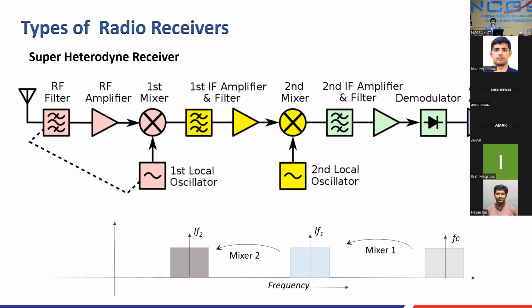I can share an example of one of my implementations where we have a 100 megahertz to 1 gigahertz input signal. Then the tuning LO was around 2 to 3 gigahertz. Then the center frequency was 2 gigahertz 50 megahertz. Then it was again down converted to around 188 megahertz with 100 megahertz bandwidth. So at IF, it was a 100 megahertz bandwidth signal with a center frequency of 188 megahertz, which could be easily sampled by 600 MSPS or 500 MSPS.